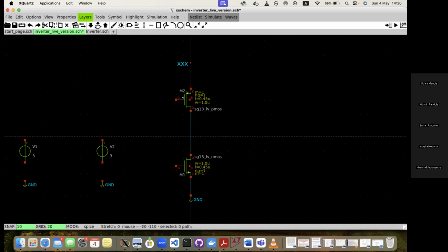In the IHP, in the MOSFET, usually you see only three terminals, but as we said earlier, when designing at IC level we have four terminals, including the body terminal. Why is there a body terminal? We can have isolated devices or a common body voltage for every MOSFET. What I'm going to do is have a common voltage for every MOSFET. This will be our highest voltage. So the PMOS body will connect to the highest voltage, and the NMOS body will connect to the lowest voltage.